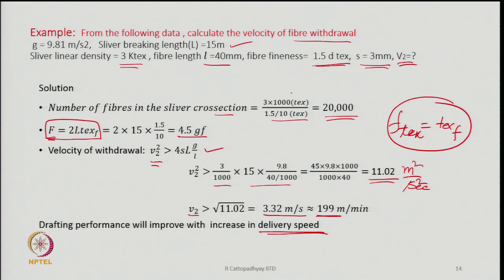So, the high delivery speed is beneficial, but for that we have to see that the roller has to be more eccentric. So, there are other precautions and countermeasures we have to take in order to make sure that the aprons have a reasonable life. So, apron quality has to improve and the quality of cords has to improve, and a lot of turbulence gets generated.